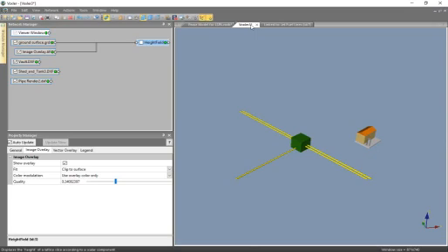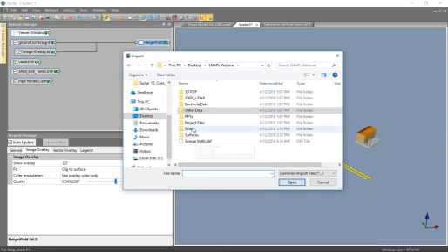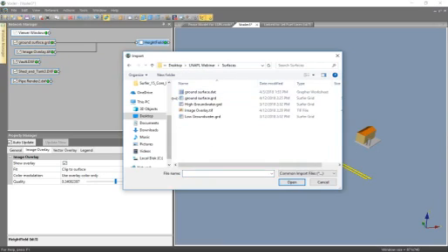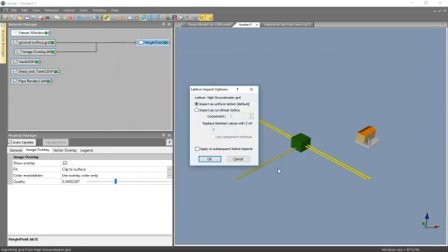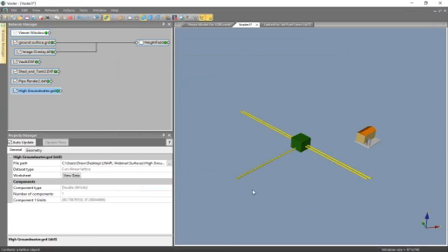So I'm going to go now and import both of these grid files using the same workflow that I used to import the ground surface. So please just give me a second here. Now, high groundwater grid. And again, we want this to locate correctly, so this option of import as a curvilinear lattice needs to be used.